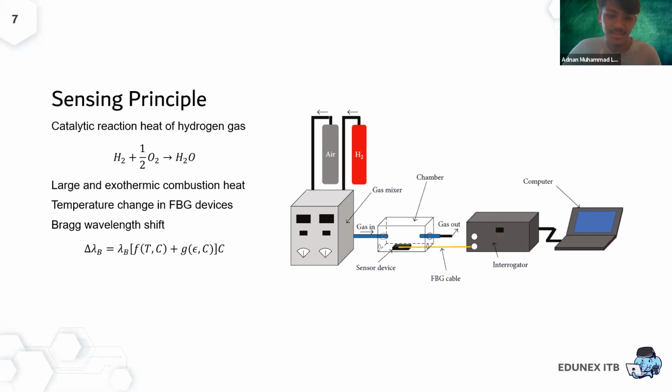And that heat will change the Bragg grating periodicity, and that will also change the Bragg wavelength, and that reflected Bragg wavelength will be transmitted into the interrogator.